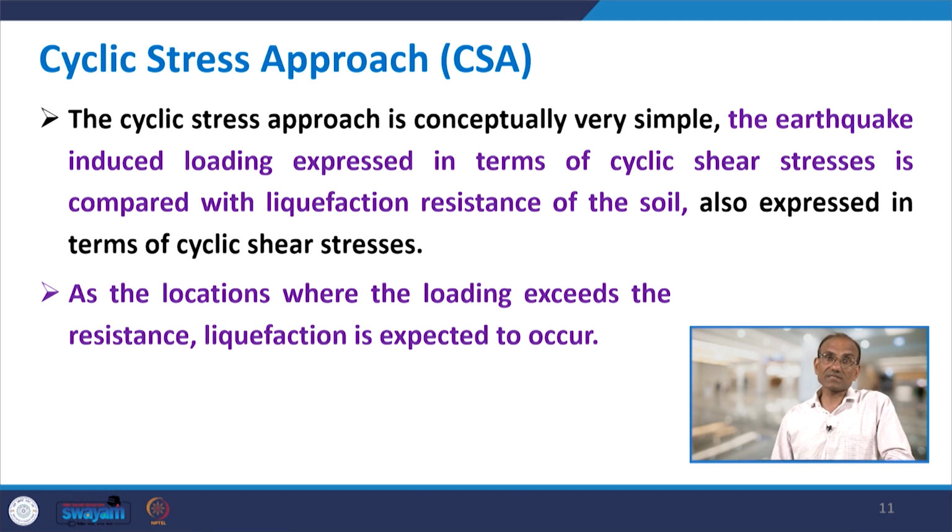Now, continue with the cyclic stress approach. It is conceptually very simple. And why is it simple? Because the earthquake induced loading, or in simple words seismic loading, is expressed in terms of cyclic shear stresses, and it is compared with the liquefaction resistance of the soil. On one side you have the cyclic shear stresses induced inside the soil due to the earthquake loading. On the other side you have the liquefaction resistance of the soil, which is also represented in the same terms, that is, in terms of cyclic stresses only.